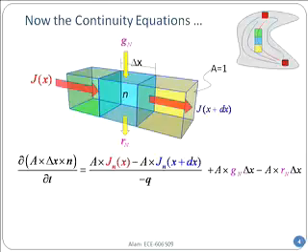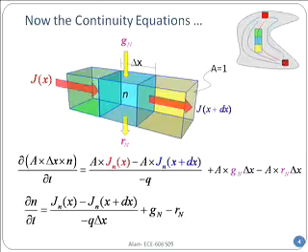You can see A is the same everywhere, so you can just divide it out. And once you divide it out, you see there is only one place where a delta x is left. Why do you see that? In the first term on the right-hand side. Everywhere else, the volume got uniformly multiplied, so everything has lost this A and delta x in the process. Now, this difference, Jn at x and Jn at x plus delta x, divided by delta x.